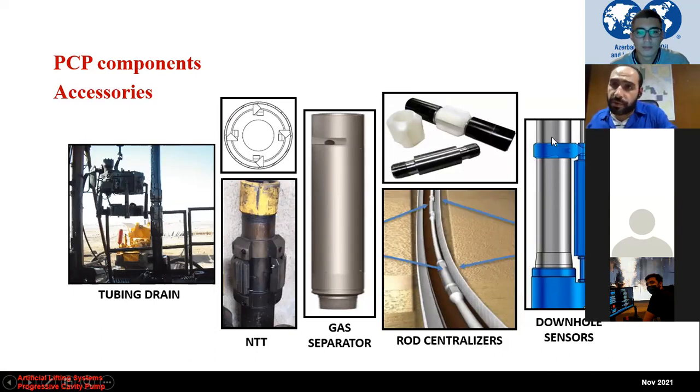So those are very important in monitoring the well, very, very helpful during troubleshooting, and they can also be connected to the VFD or the electric panel and allow some advanced applications. In cases like the pump is pumped off, there is no fluid level, the intake pressure is not enough, you can easily program the VFD to take an automatic action, reduce the speed as the fluid level drops below a certain value, and then speed up again if it exceeds that value. So very smart and very useful parts.